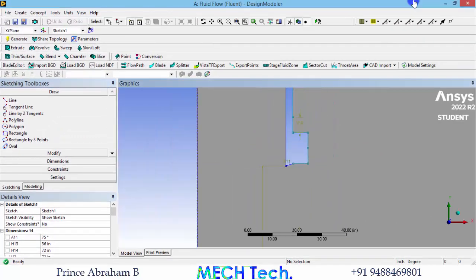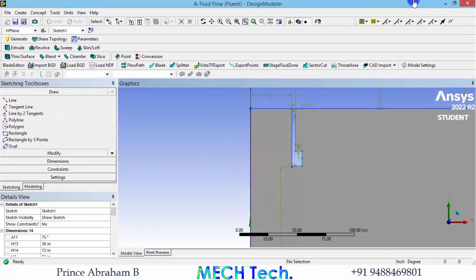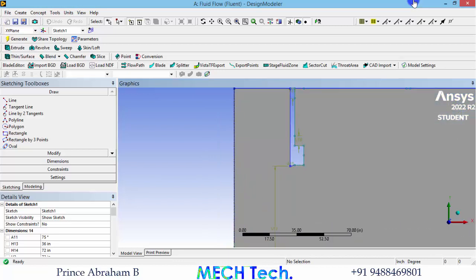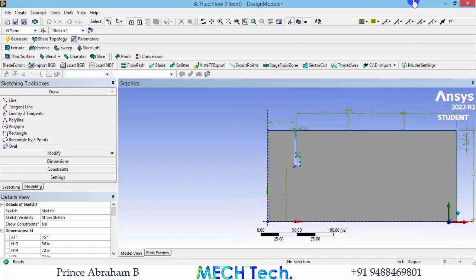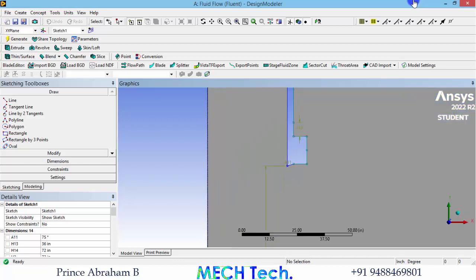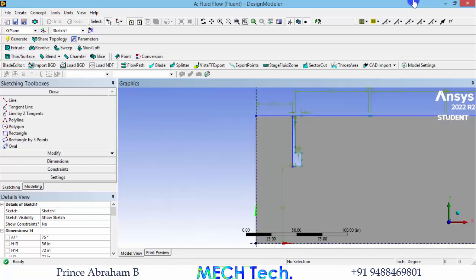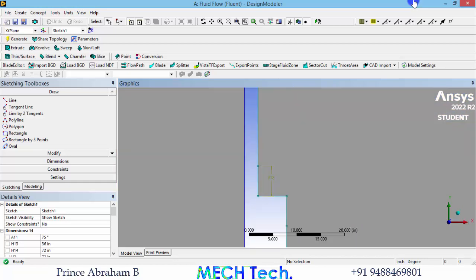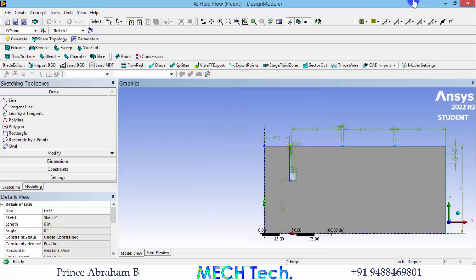So this is the angle of the inlet of the air curtain, from which the air at high velocity is blowing in order to create a recirculation zone here, so that it will act as an air barrier, just like a virtual door. When the air gets in through this air curtain, it will be dumping into the room, so that should be recirculated some way. There is also an intake port for this air curtain, that is this particular port. So this is considered as an intake port for that air curtain. And finally, this is the interface where the room has an atmospheric interface.